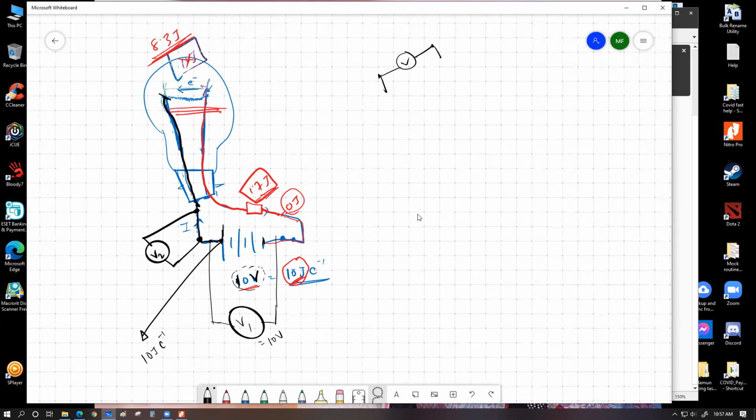So there is no voltage drop whatsoever, which means that if I connect 2 points over here, or even if I just rub this off, and assuming that the filament lamp works fine even if we break the glass, assuming that if we even connect the voltmeter right over here I'm still going to get 0 volt because there is no energy conversion happening across these 2 points. There is no resistor over here. We don't have any energy conversion, which means that electrically they are the same point. The voltage over here and the voltage over here are practically the same.